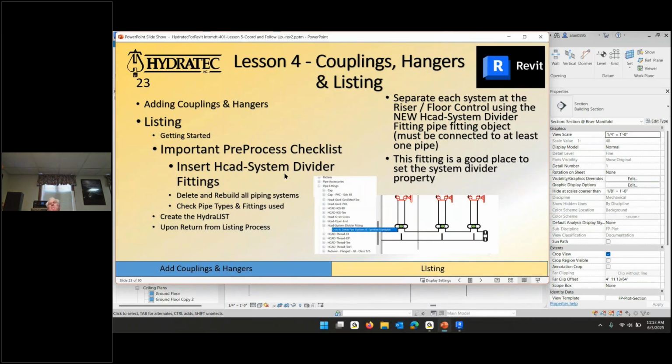Revit has a built-in habit that every time you create a pipe, it says, oh, that pipe could affect my neighbor, and my neighbor could affect his neighbor, and his neighbor, his neighbor. So I'd better go check all through all of those connections and find out what was affected by your just doing this one pipe. Once you get 2,000 pipes, that takes way too long.